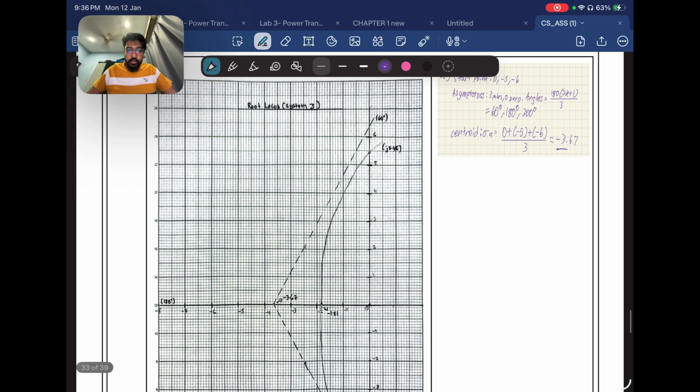And then for the design, I choose 50 because it is more than 24.2 critically damped, it should be the perfect one, because usually the damping will be 0.5, natural damping. So that's why I choose this design 50. So here this is why I use PID for the new system, and I use 20 because it will eliminate faster. I can get exponentially 2 times faster, as the question said. So yes, I get 2 times faster from here.